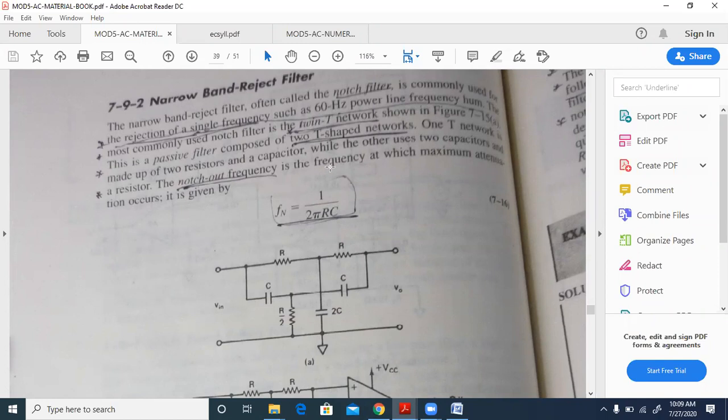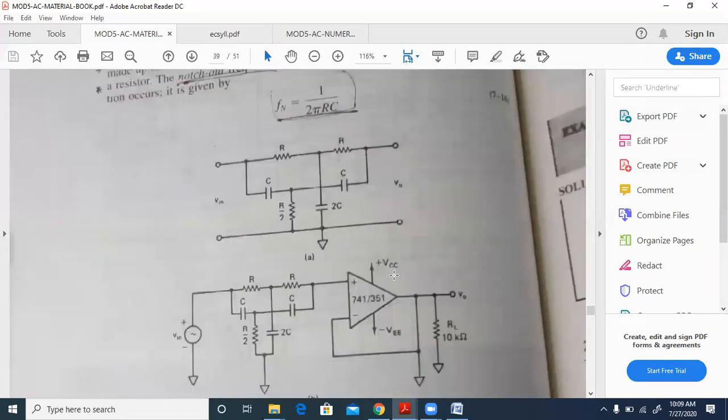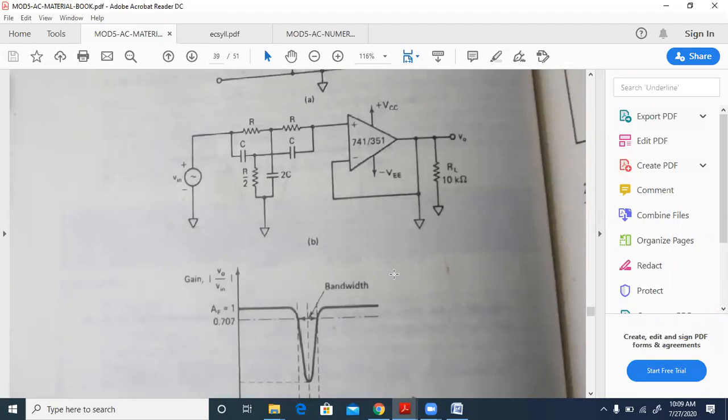Only in the second ordered case, you'll have two sets of resistors, R2 equal to R3 equal to R, and C2 equal to C3 equal to C. That's all. So formulas do not change much. Only the response formula might change. One might be addition, another might be multiplication, depending upon whether it is band reject or band pass.